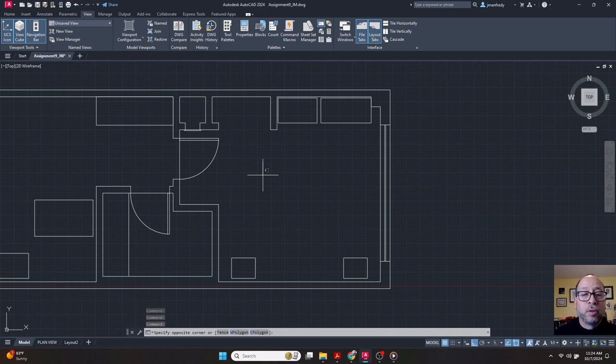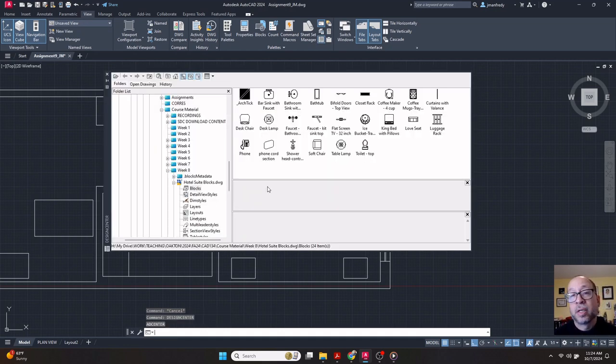If you're drafting, if you type quickly, you can simply type the words Design Center, it's one word, and enter, and it launches the command immediately. In the event you forgot where the icon was located, or in a newer release of AutoCAD they moved or relocated the icon in the interface, simply understanding the typing commands is very quick, and they rarely change.